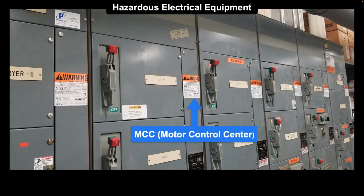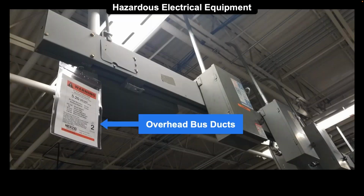Overhead bus duct, we like to make our labels a little larger. So 8.5 by 11, fold in half, clear sheet, they hang from the bus duct. You can't miss them. Our goal with this is you can be on the ground and look up and, in this case, see a giant level 2. I know I need to put on a minimum of level 2 PPE. And we place them every 30 foot. The goal with that, you can look left, you can look right, you're going to see an arc flash label. You cannot miss it.